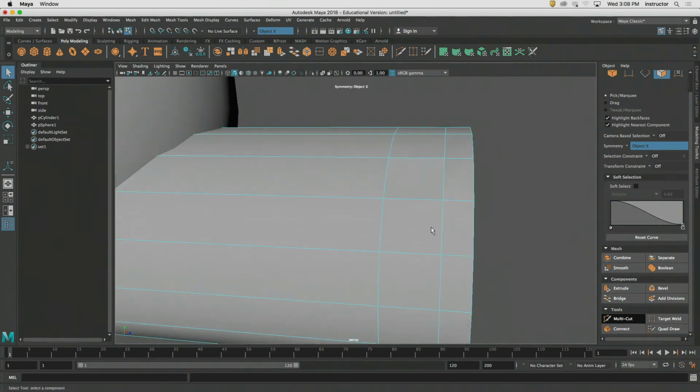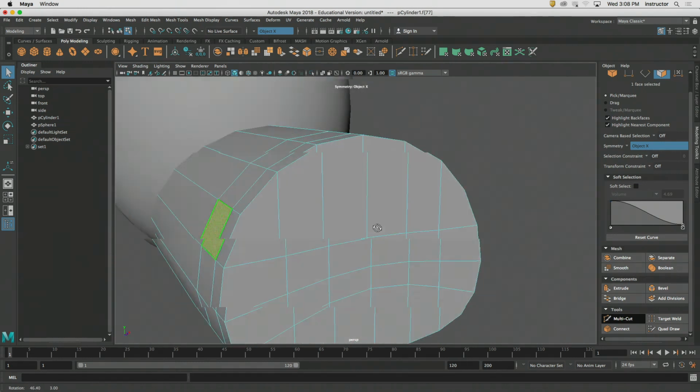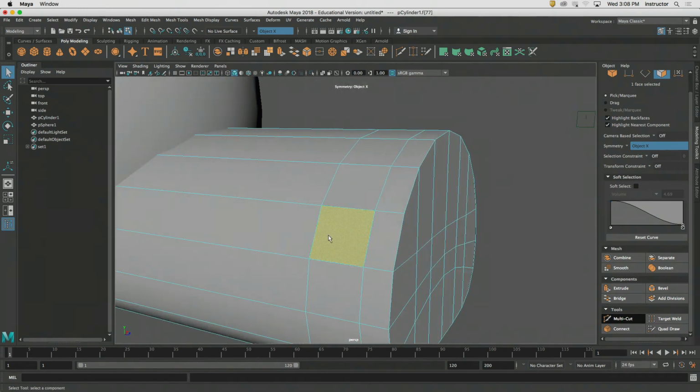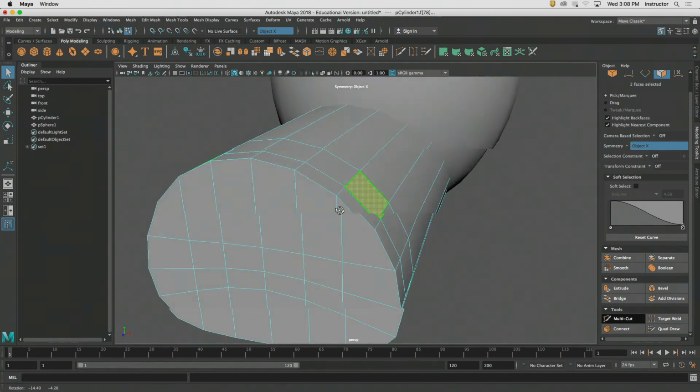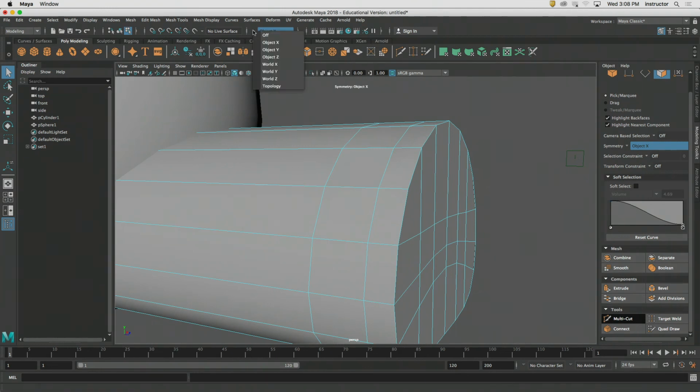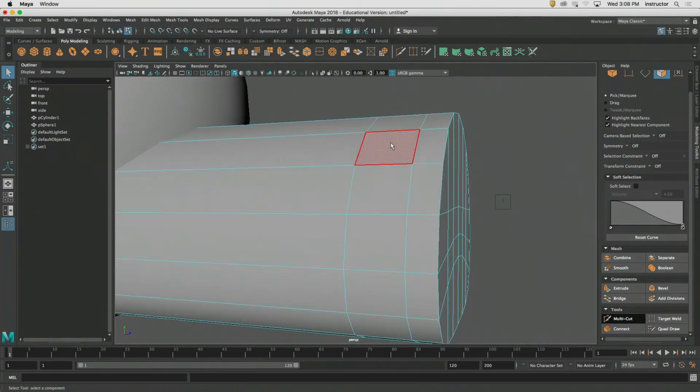Now, in order for us to create a circle right there on both sides, okay, I need some more geometry. There's only four verts that comprise that surface. At the very least, I'm going to need 6, maybe even 8 if I'm lucky, but 6 will at least start the conversation. It will generate a surface that's generally circular. Because I'm super OCD, I would really, really like to have an edge loop running down perfectly in the center here, okay?